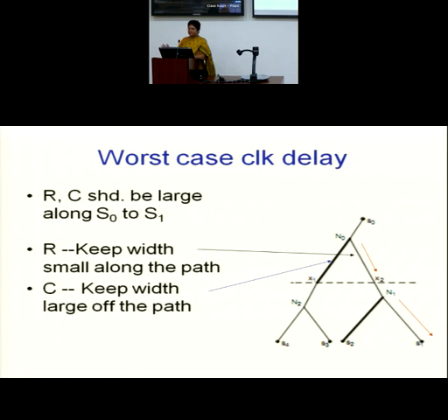I have to find out a setup for myself. In what way should I compute the delay? That will be the maximum delay and the minimum delay. As I know, delay is simply the RC product. So the worst case delay is R maximum, C maximum, and the best delay is R minimum and C minimum. Now I have taken one decision that the width will always be minimum possible. So the width is fixed.